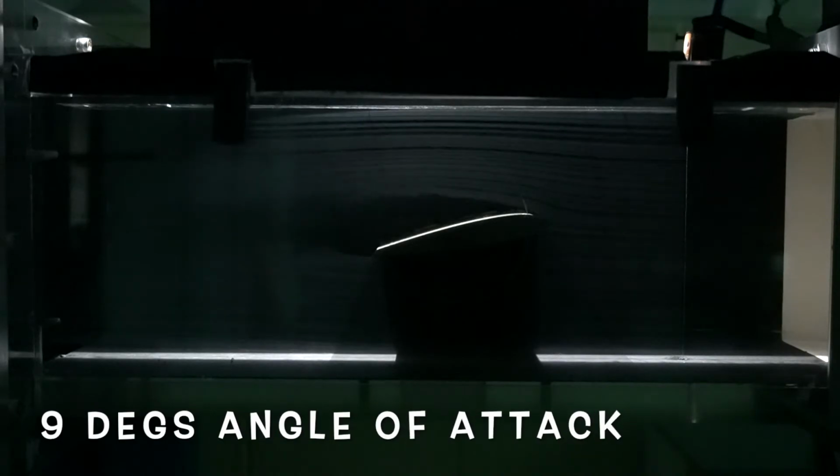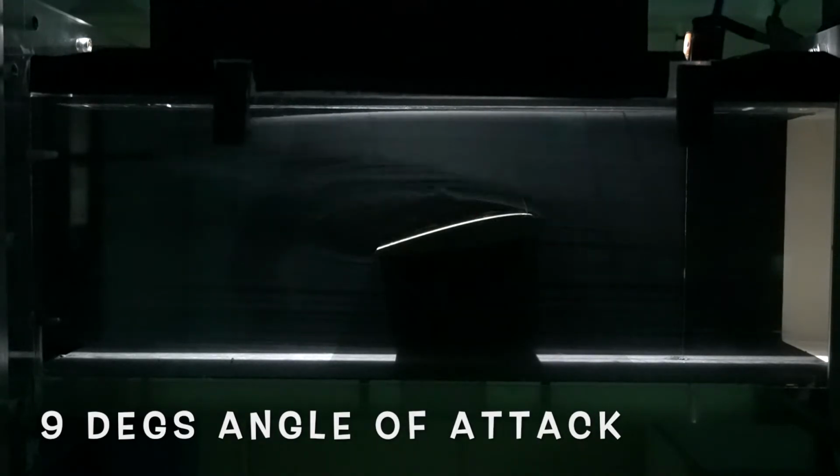Yep. So now we've moved up to an angle of attack of 9 degrees. So now we're in the partial stall regime. And if you look at the streamlines, you can see that they're no longer attached to the airfoil all the way to the trailing edge. You can see that the separation point has moved up closer towards the leading edge, but hasn't reached the leading edge quite just yet. It's separating about a quarter or a third of the way down. Stall us, baby.